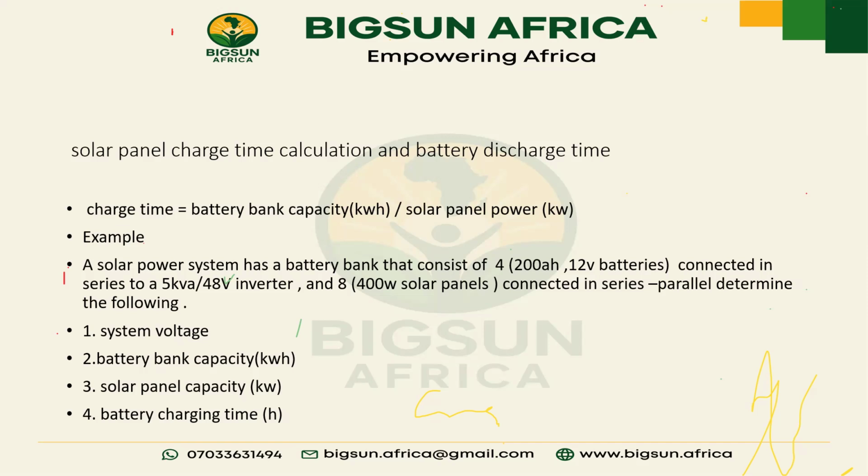So 12 volt 200 amps in kilowatts is 12 volt times 200, which is 2,400. Then times 4, because we have 4 pieces, that is 9.6 kilowatt hour.